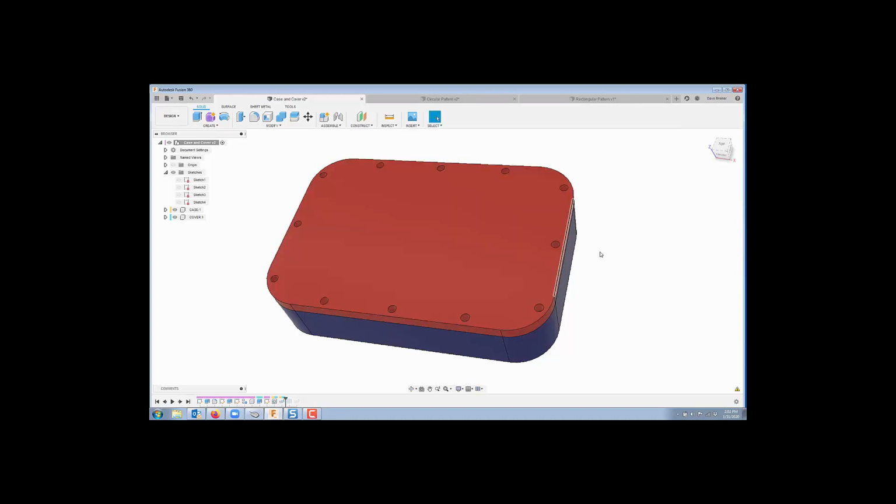On rectangular shapes, you can do this on a path. If you have a part and then you have a sketch line that takes that on a curve, you can do that. So any path, just happens to be this one here. So again, you can have any part or feature drawn out that has a secondary sketch with another line or curve drawn out, and you can pattern that along that sketch line. So this is a nice command. It comes in very handy. I kind of like it. I find this to be a real life application, at least for the way I work.